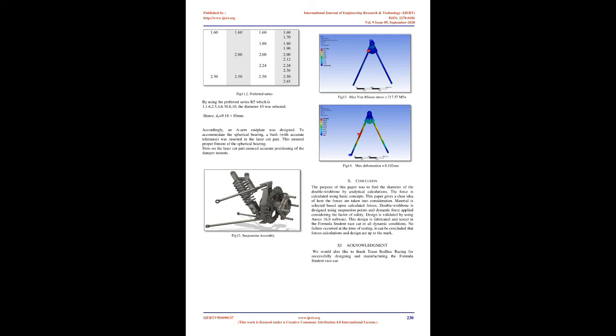5. To determine loads, restraints, and material properties, pen and paper calculations played a vital role. 6. The FEA results verification and validation with an independent set of calculations are crucial to provide confidence in the analysis results. Design philosophy. Choosing suspension geometries and components involves a wide range of choices and compromises. An analysis of the tire, suspension component, chassis, and road interaction is required to decide the trade-offs that will result in an optimum configuration for the type of vehicle.